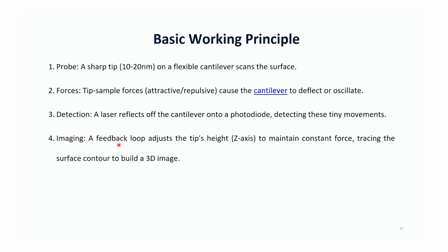Then imaging: a feedback loop adjusts the tip's height on the z-axis to maintain the constant force, and this traces the surface contour of your sample to build a 3D image of your sample.